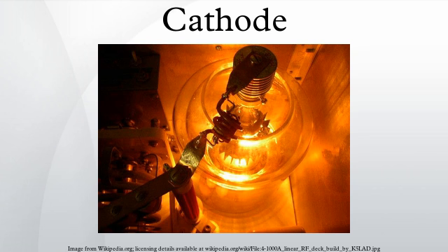The main reason for using an indirectly heated cathode is to isolate the rest of the vacuum tube from the electric potential across the filament. Many vacuum tubes use alternating current to heat the filament. In a tube in which the filament itself was the cathode, the alternating electric field from the filament surface would affect the movement of the electrons and introduce hum into the tube output. It also allows the filaments in all the tubes in an electronic device to be tied together and supplied from the same current source, even though the cathodes they heat may be at different potentials.